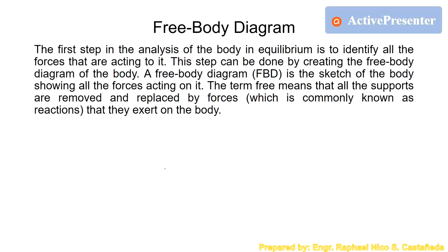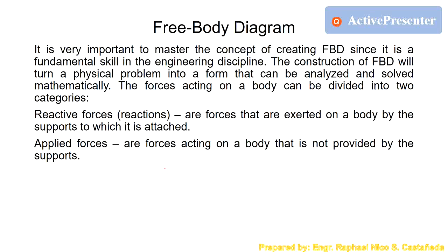A free body diagram is basically a sketch of the body showing all the forces acting on it. The forces may be reactive forces or applied forces. The term free means that all the supports are removed and replaced by forces, commonly known as reactions, that they can exert on the body. It is important to master the concept of creating free body diagrams, since it is a fundamental skill in the engineering discipline. The construction of an FBD will turn a physical problem into a form that can be analyzed